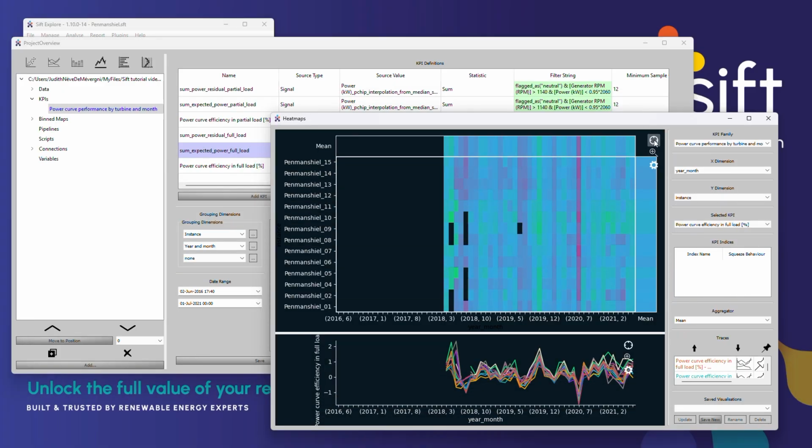There are many possible reasons for the observed deviations in power curve efficiency. These include changes in turbine control, imperfect data cleaning, and measurement issues, often changes to the turbine anemometry. In this series, we have shown the building blocks of setting up an analysis on operational wind turbine data. We hope you feel empowered to use these in setting up your own analysis.